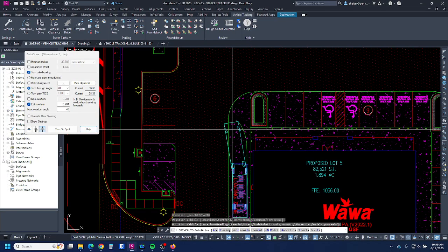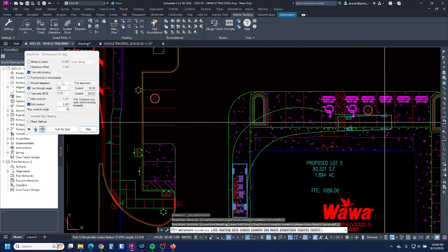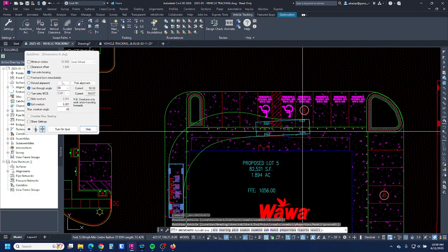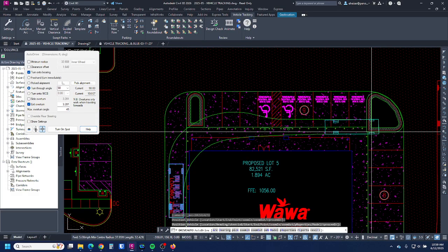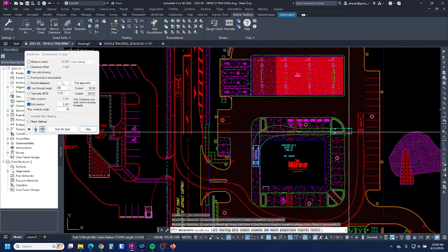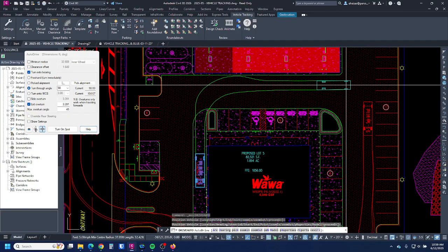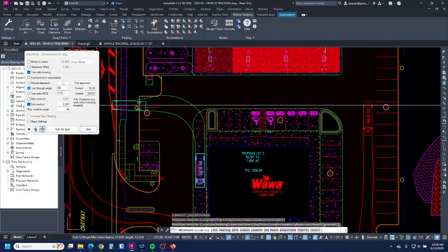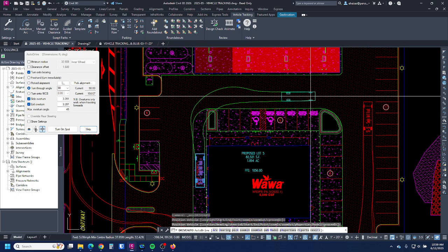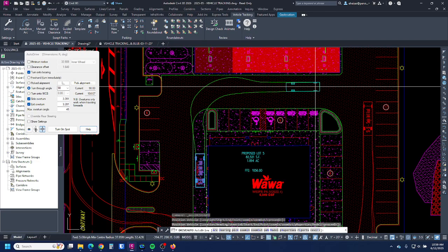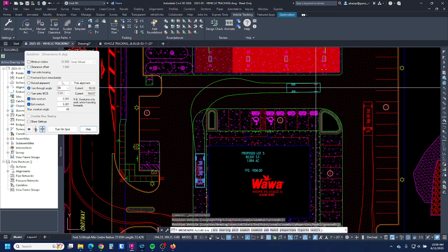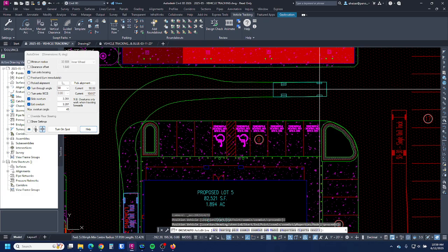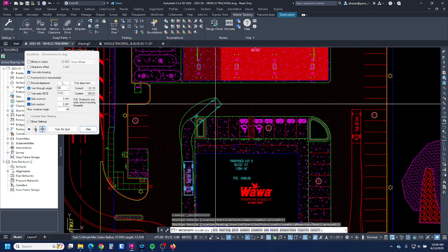If I do exit overturn, it overruns the curve a little bit and actually turns itself further than you want it to, kind of overcorrects a little bit. So these are both things that can sometimes come in handy, sometimes not. They're usually worth trying if you're having trouble. You can also use both at the same time if you want to. In that case when I added the side overturn, now I'm not jumping the curb whenever I make that. So those are options you can do.